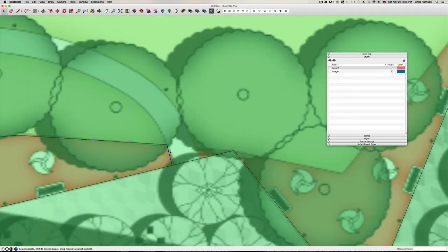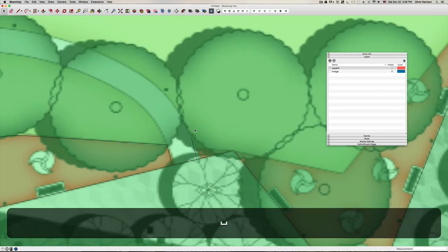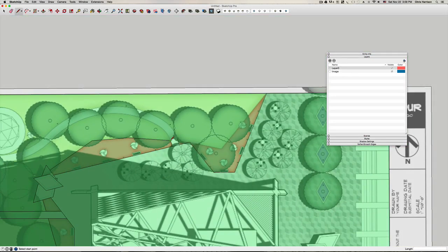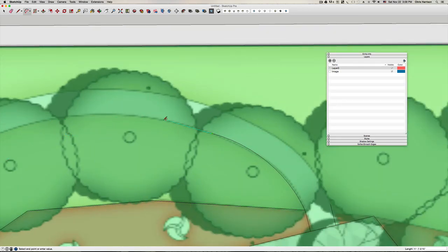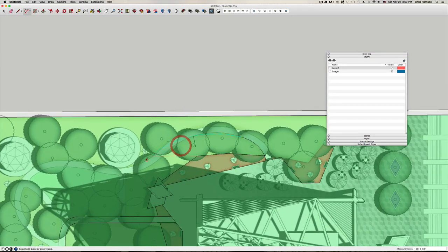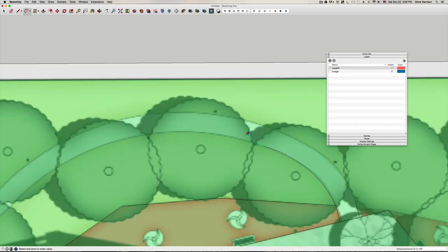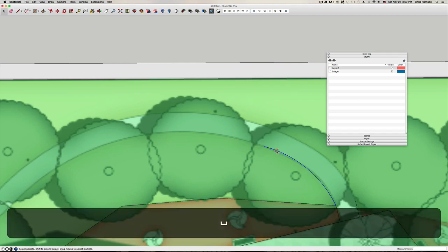And actually, another way of doing that too is I'm going to hit M for my move tool and hold, I'm holding Alt, I believe it's Control on a PC. And I'm come over on the axis, I'm going to type in 6 feet. And it'll give me my point there as well the same way. Hit A for my arc tool. Looks like it's doing something like that. I'm doing this quickly so I can, well, still be accurate though. Let me delete that.